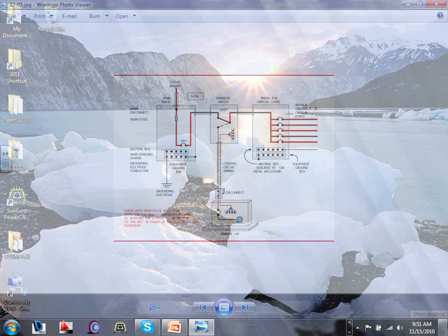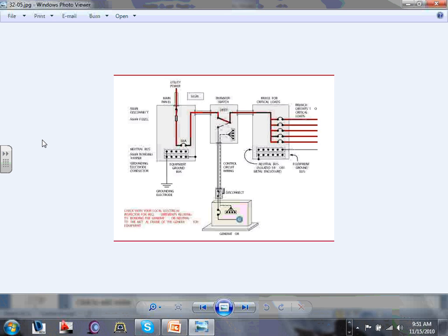Another application, if you have the money, look what they did now. This is more of an auto transfer switch, guys. I have the main panel, a sub panel, a generator and an auto transfer switch. Instead of having this mechanical interlocking, now they have a full auto transfer switch or manual transfer switch. You could buy a manual transfer switch with one move. You shift from the utility to the generator, auto or manual or static.